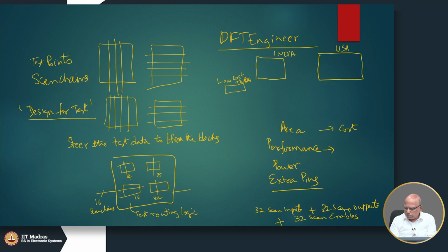See, this is a lot of pins, right. So, people will frown and say, we can't possibly give you that many extra pins, right, because pins are expensive. Okay. When you add more pins, you will have to go to the next level package, okay, and the more pins in the package, the more expensive the package becomes. Okay. So, this is prohibitive.